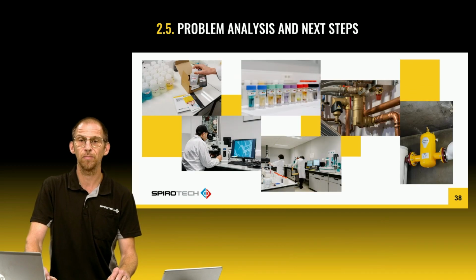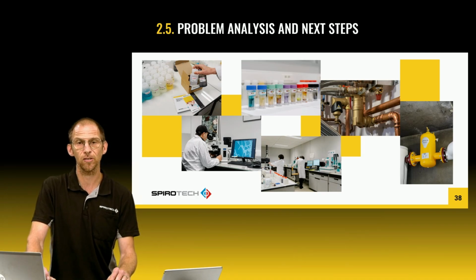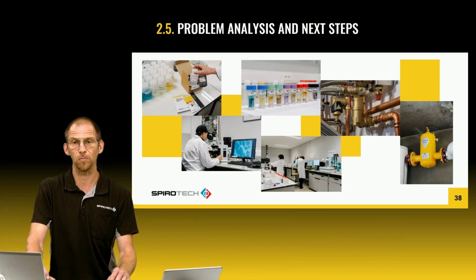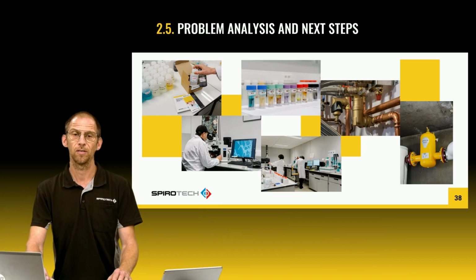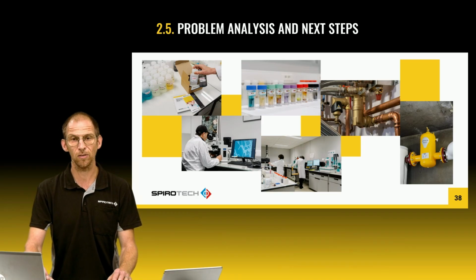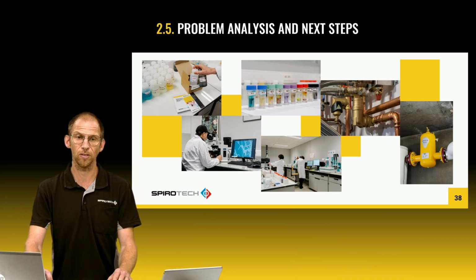Now, to bring the system back into the right water quality range, combine the correct application of a pressure maintenance system with a water analysis to find out which corrective measures need to be taken. This analysis can be carried out by the SpiroTech laboratory. To remove accumulated air and dirt, use air and dirt separators. This stabilizes the circuit, protects components and recovers efficiency.